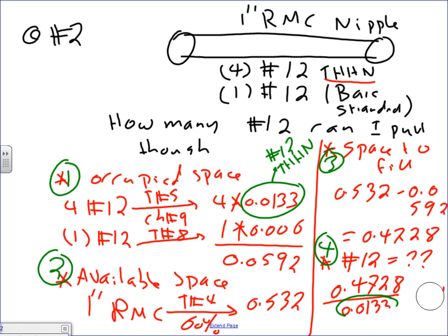That's why I really like you guys to give me the answer. Everybody came up with 35.5, and that will translate to 35. So I can only have 35 conductors. Thank you, Rob. 35 conductors. Any questions, guys?